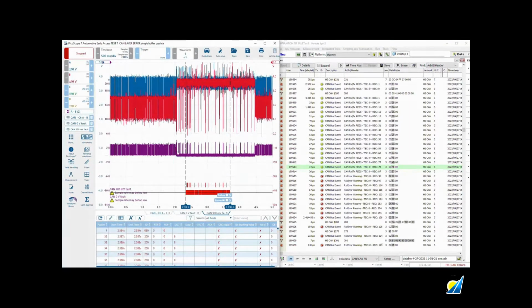And we can see during this period when the CAN bus was driven high, how there was some form of communication still ongoing. Because the network was down for so long, approximately 2.5 seconds, that was enough to send the error counters sky high, as we described earlier.